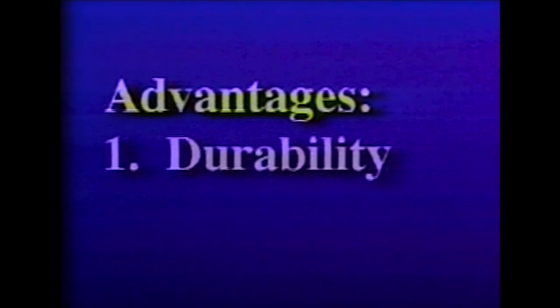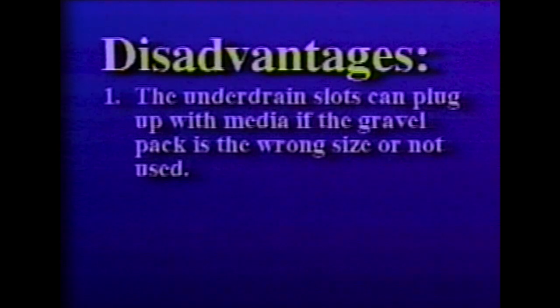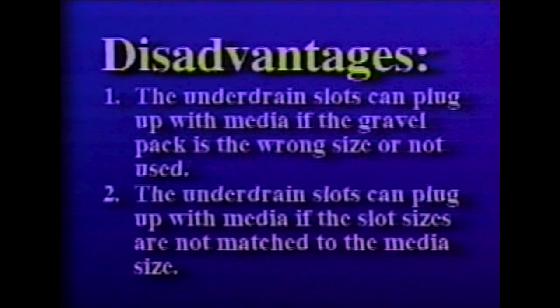These slotted underdrains have become popular because of their advantages. These advantages are durability and serviceability. There are disadvantages, however. The underdrain slots can plug up with media if the gravel pack is the wrong size or is not used. The underdrain slots can also plug up with media if the slot sizes are not matched to the media size.